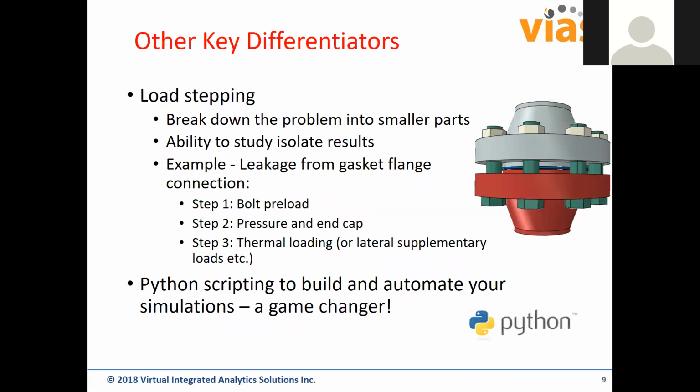a step above the rest, is the capability to do, number one, the load stepping nature. That is, you are able to break the problem down into smaller bite-sized pieces. You could do it to simplify your model development, or you could even do that, as shown over here in this flange case, to replicate the true nature of application of the loads. For instance, in this case, we first apply the bolt preload as we would when we're tightening a flange, proceeded with pressure and end cap loading, and finally as the